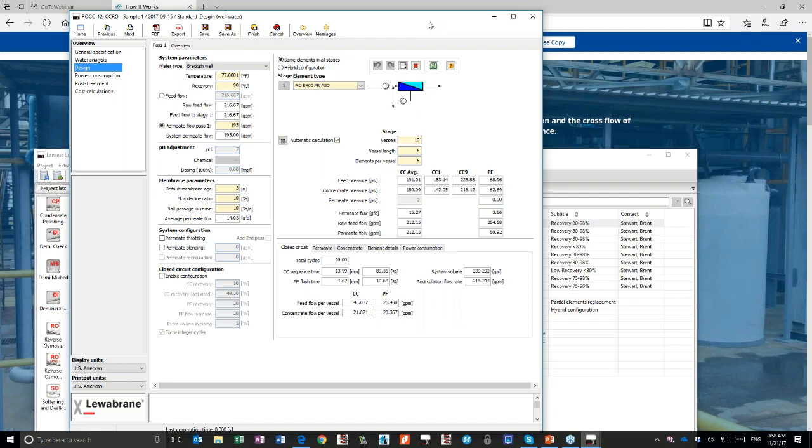Yeah, so what we tell people, if they're going to run their own scaling projections, is to run them to just 100% saturation, or to the maximum the program allows. So that maximum in a traditional system would be a red flag. Typically, you would only design to 80% to give yourself a buffer. But the 100% saturation, or pushing the limit of the scaling projection, that's the bottom of our guarantee.